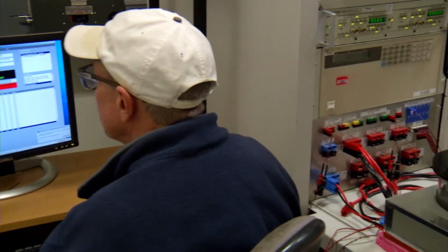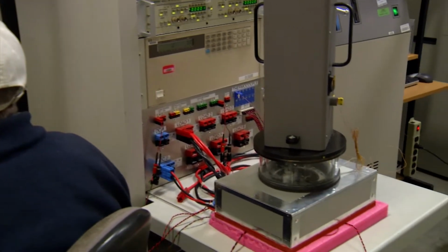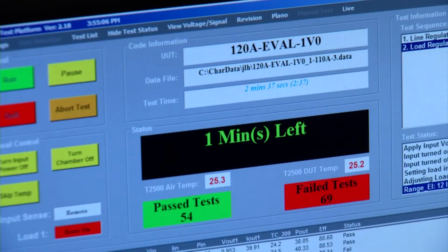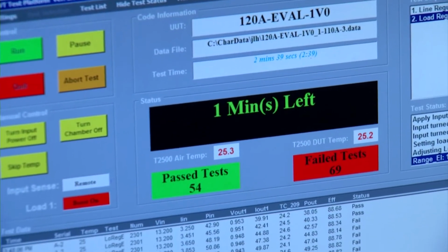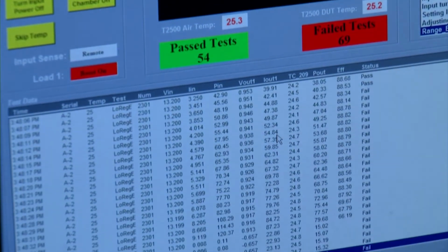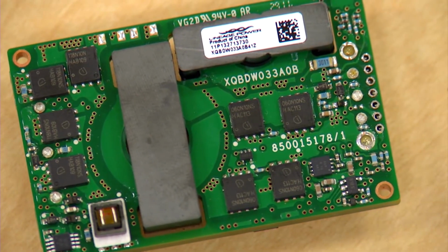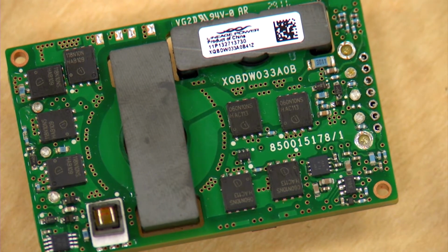To verify that the module is operating correctly and as expected, prior to the thermal testing, a complete set of efficiency and power dissipation curves of the test module are obtained via automated testing at various ambient temperatures. Next, the critical components must be identified and thermocoupled. Critical components are those components that limit the thermal performance of the module.